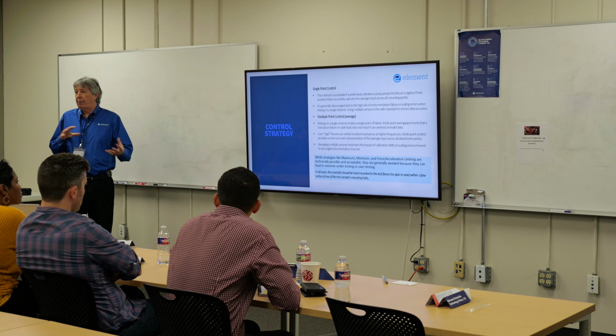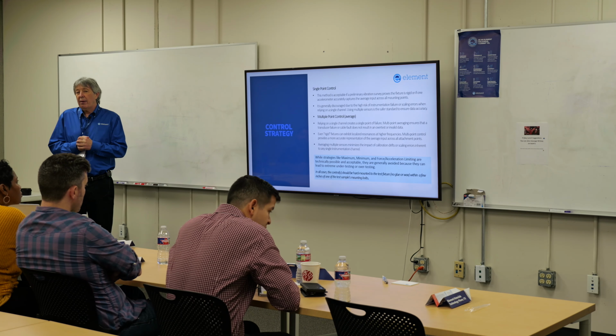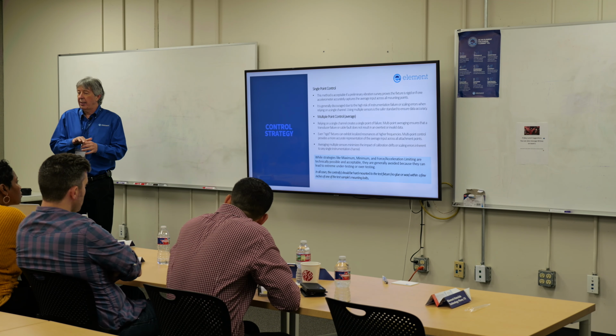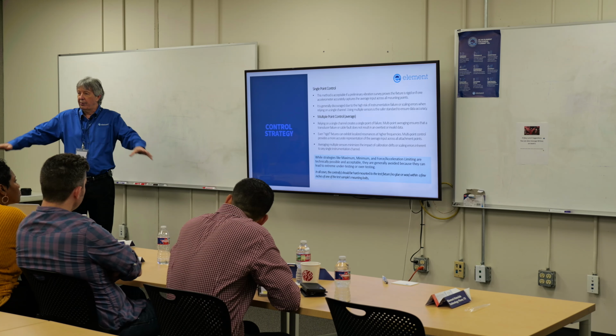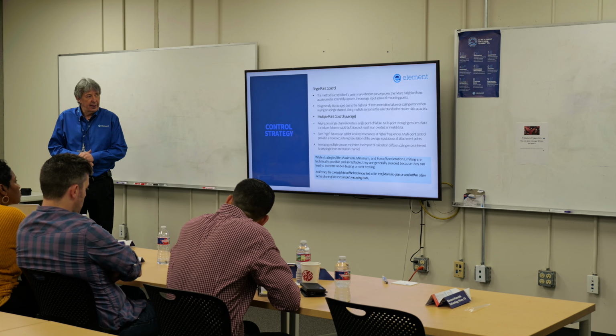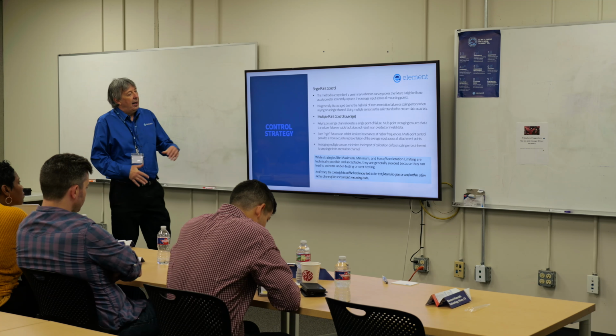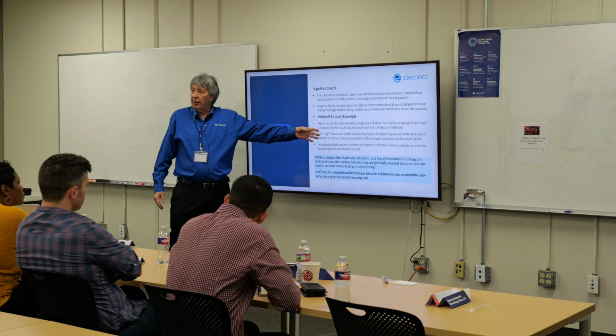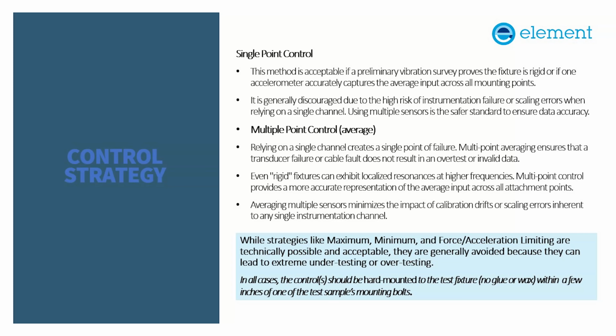A10 allows you to do a couple of different control strategies. When you run vibration, the control accelerometer, where it's mounted, is the only place on that table we know exactly what's happening, because aluminum is like an ocean. Frequencies travel differently through the water. So here we like multi-point controls. There's a couple of reasons why. A10 allows you to do a single point, which is fine, but 99 out of 100 times we'll do multi-point. We like to use cross corners.